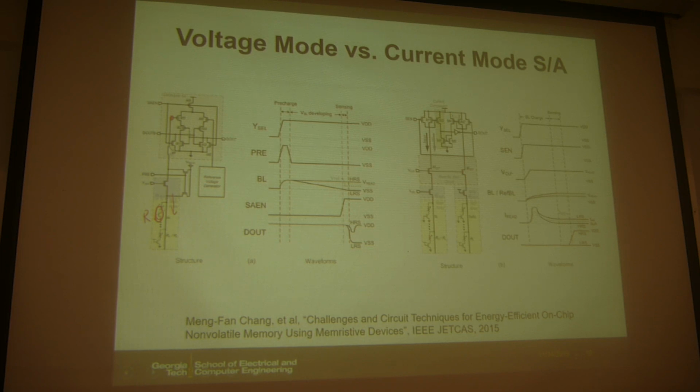So essentially this can be divided into a few steps. First one is pre-charge the bit line. You pre-charge this bit line to a high value. So your bit line starts with some high value. And then after you pre-charge, you turn off the pre-charge. Now you turn on the word line in this case. So then, depending on the resistance here, the current can be large or can be small. If current is large, then you are going to decay this node faster.